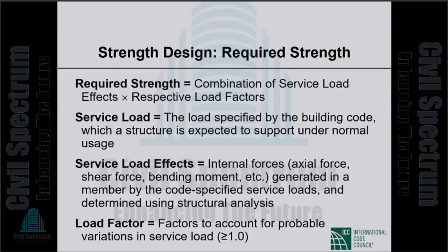We factor the dead load moments by one factor. We have factored dead load moments. Then we have factored live load moments. The live load factor is different from the dead load factor. Then we have factored wind load moments. Wind load factor again is different, but these factored load effects are combined, and that gives us the required strength.